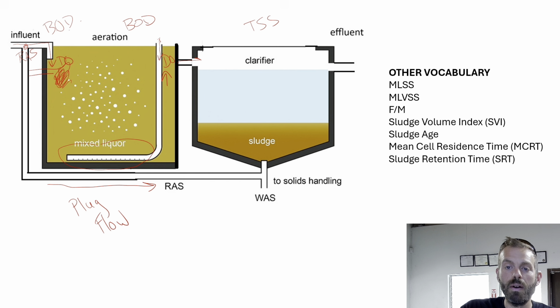In the clarifier, what has occurred in aeration is these microorganisms have created what's called floc, okay? And so there's young sludge, there's old sludge, and typically younger sludge is going to be light and fluffy, hard to settle. The old sludge will be really compact and easy to settle, but so small that it might leave some pin floc behind that floats, and you can't get it to settle without chemical assistance, and they would end up leaving the plant in the effluent.